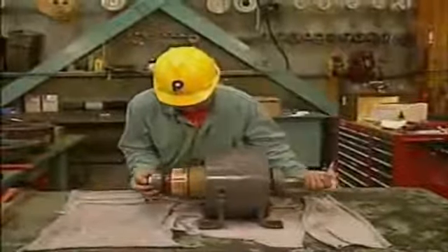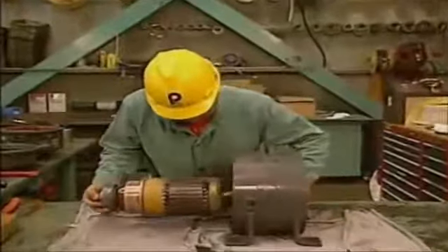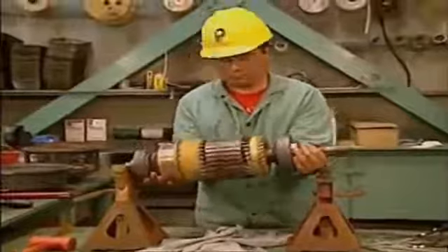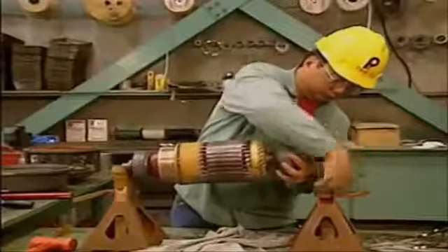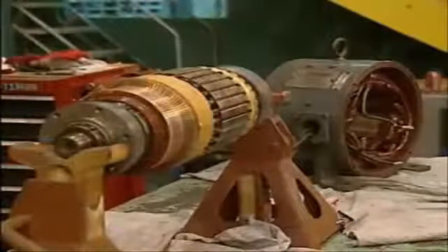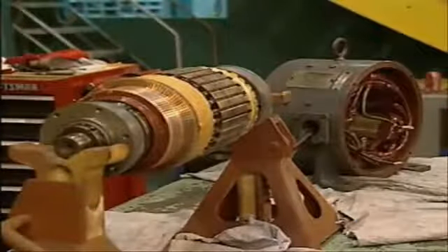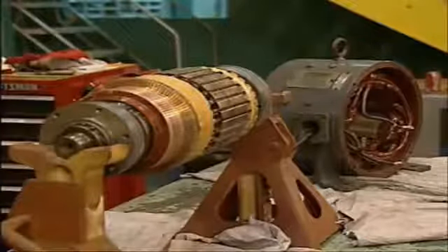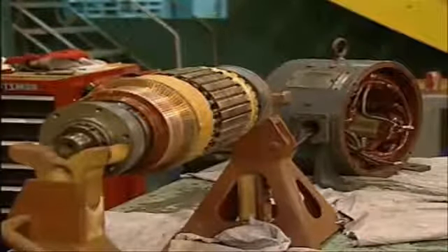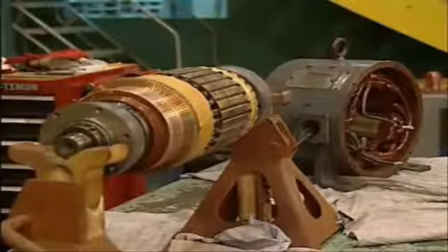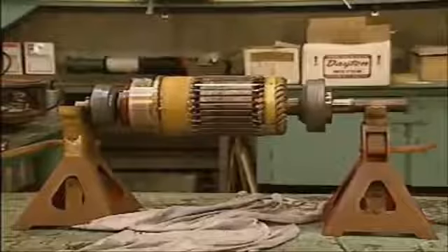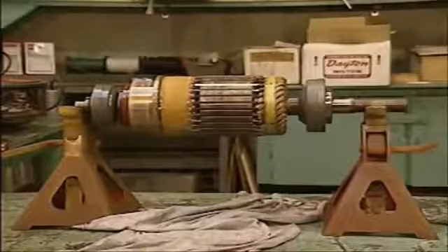The armature should be lifted, moved carefully out of the frame, and set down on a cloth or V-blocks, or, as in this example, in a pair of stands. This completes the disassembly of the motor, unless your company's procedures require the motor's bearings to be removed as part of an overhaul. If the bearings have to be removed, a bearing puller may be used. Take a moment now to check your understanding of what's involved in disassembling a DC motor.